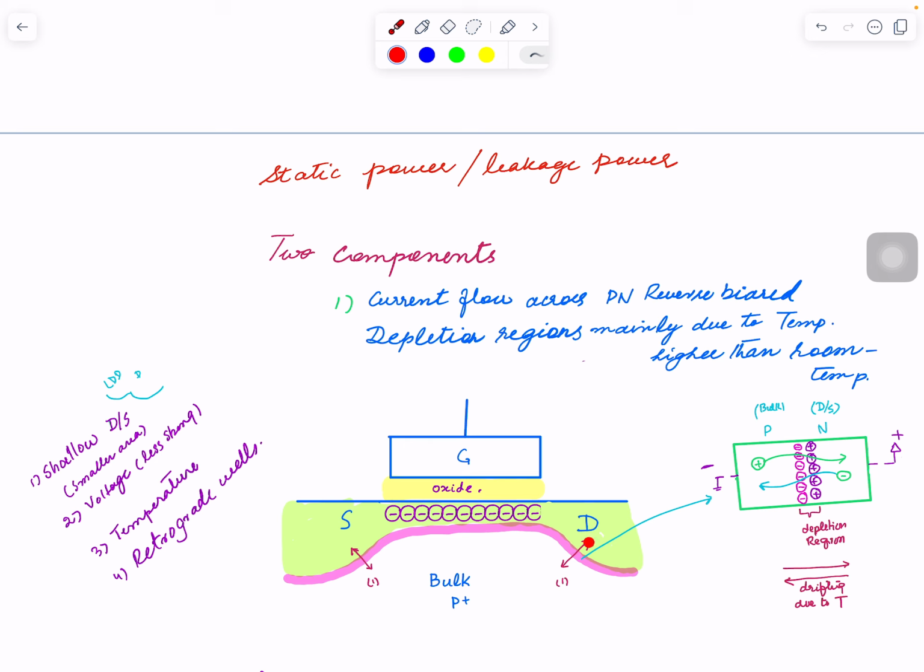And if current starts leaking here, you will see that even when you don't want any current flow, some current is flowing through. It's finding a path here, and here, and here. So your electrons are wasted, your voltage is disturbed, and it's no longer the ideal switch that you really wanted. So it's really important that we have this wall, this barrier here. This is the way to create walls at the transistor level, this depletion barrier.